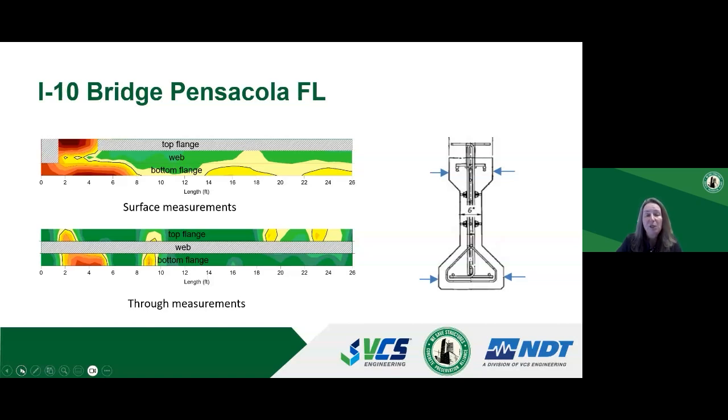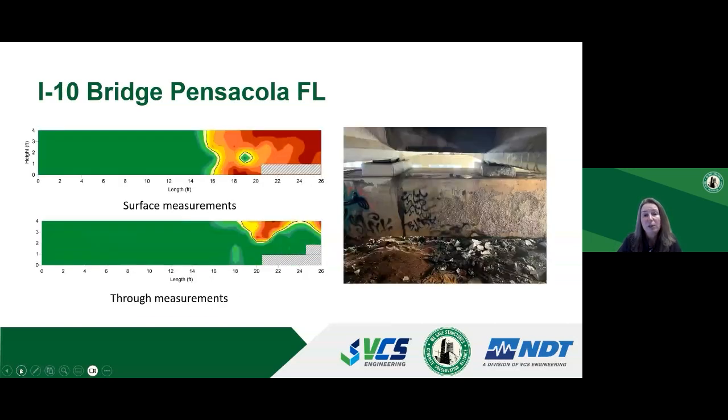However, we're placing the impact device on one side of the element and we're placing the sensor on the opposite side. So in this configuration, instead of looking at the near surface concrete, we're looking through the entire thickness of the element. And this is illustrated on the schematic on the right side of the slide.